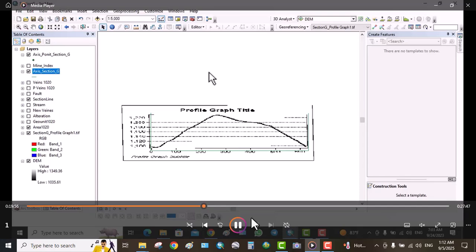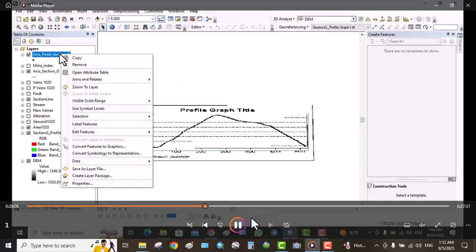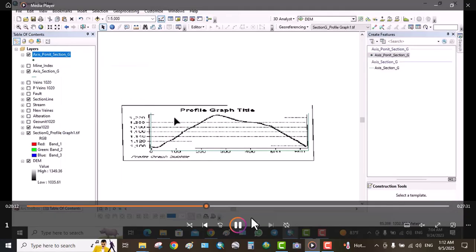parallel to the first vertical line. Click absolute option, type X as 630, Y as 1240, right click and select Finish Sketch. The chart is created. From the Editor click Save and then Stop. Next, create points on the graph.